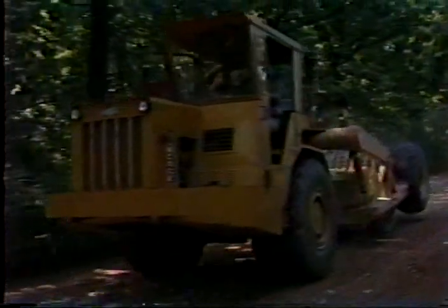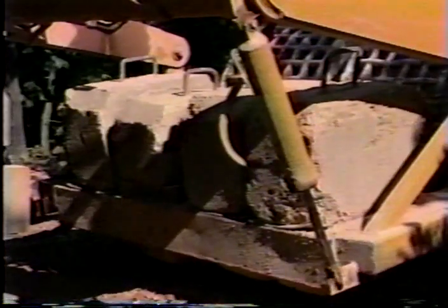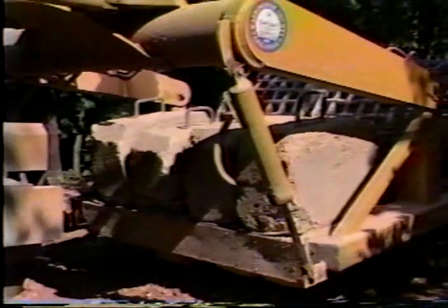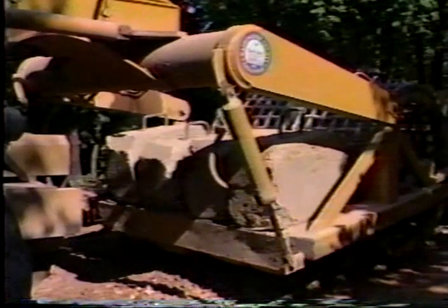This method involves the use of a grid roller constructed by modifying a self-powered earth-moving machine. Using concrete weights and a heavy steel grid roller, this machine is driven over the windrowed aggregate, effectively reducing many of the large rocks to usable subgrade material. The crushed aggregate can then be remixed with the underlying fines and gravel and reshaped into a cohesive wearing surface.